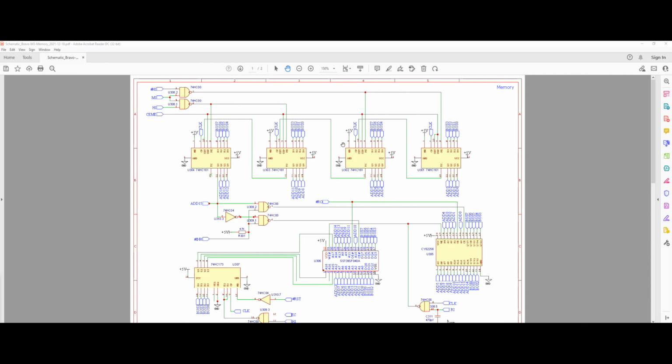memory address register. And that's why you see that the 2 chips on the right-hand side are connected to bus 0 to bus 7, and the same thing is happening on the left-hand side. Again, the 2 chips on the left-hand side are connected to bus 0 through bus 7. So the input side obviously requires control logic so that we can go through that sequence of reading data from the bus for both sides.